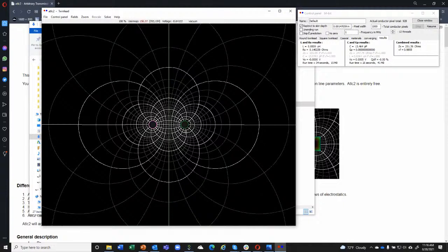Energy is between the charged conductors. That's where the energy is densest, but energy goes outside of it as well. And this is why in a printed circuit board, if you have a transmission line microstrip and it goes away from the reference plane, it becomes effectively an antenna. Antenna, right. And you get EMI problems, you get radiation.